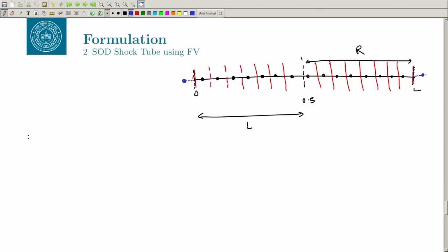Let us say we first consider faces, like in the finite difference formulation. Let us say you have divided into 101 parts, so you have 101 faces. The actual cells will be 101 minus 1, which is 100. You can count it here: 1, 2, 3, up to 15 cells, and if you count the faces, 1, 2, 3, up to 16. So the one extra face is only valid in 1D.